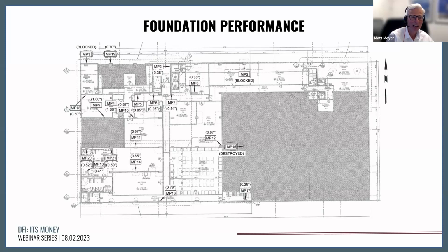So this particular slide shows the foundation performance of the building 1 month after topping out the tower. Remember, the tower was 25 levels. This particular slide shows a snapshot 1 month after top out, but the way this data was obtained is we instrumented the shear walls and columns. And what we did is every 5 floors, we would survey the monitoring pins installed into the shear wall and the columns, these Tapcon type concrete nails or screws. We would survey those every 5 floors as the high-rise building was constructed.